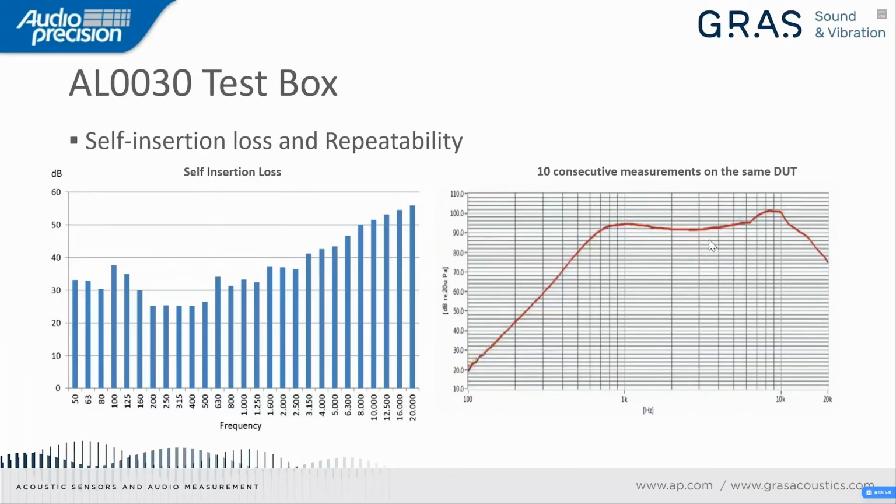So the way these test chambers are used is the following. First of all, we select a golden device. This could be a tablet or laptop that, after proper testing in a hemianechoic chamber or with a trained listener, we all agree is performing in the way we want. Once we do that, we grab this golden device and place it inside the test box and perform the required acoustical tests.